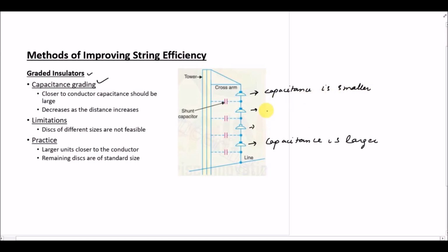We know that if the capacitance is increased, then Xc, the capacitive reactance, will decrease, because Xc is equal to 1 over omega C. So if we increase the capacitance, Xc will be reduced. Now, to find the voltage across the insulator closest to the conductor, the formula is V equals I, which is passing through this particular insulator, times Xc, right?